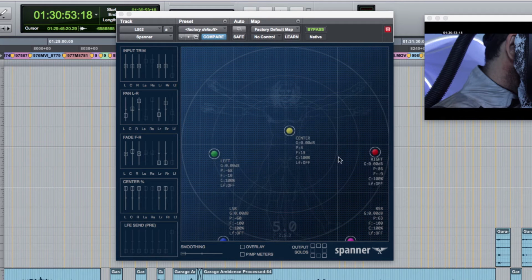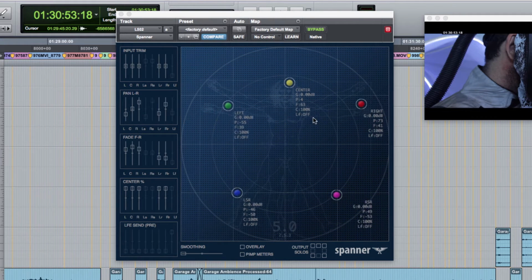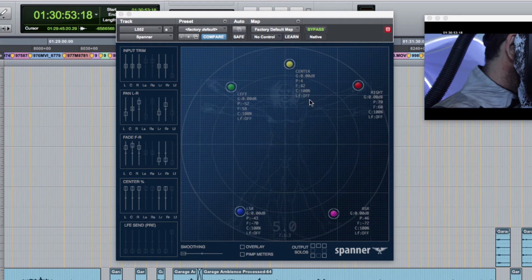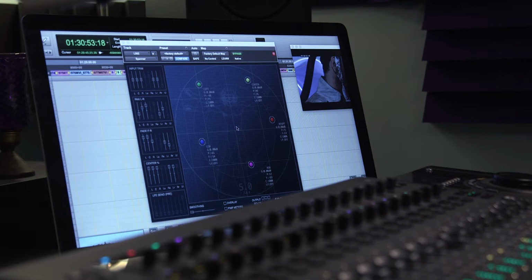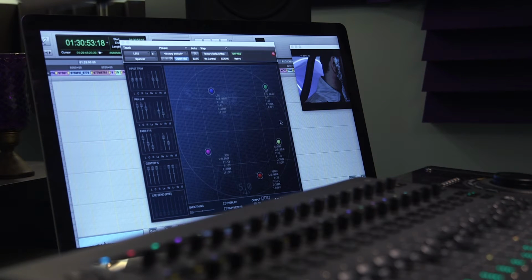Holding down the Option key plus Control or Shift gives us the same function, but in turn controls all pucks at once, instead of just front or rear pairs. Control, Shift, Option, and dragging right or left lets us perform a very cool feature: the ability to rotate the relative position of our pucks.